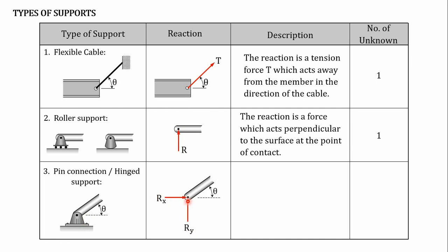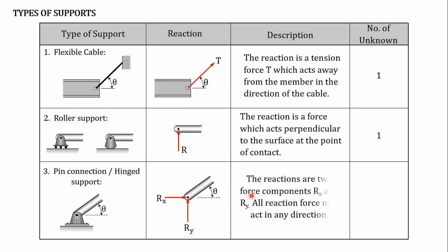But take note class, pin connection can rotate freely. When the bar rotates freely, there will be no resistance in moment. Therefore, walang resistance in moment dyan class. Only Rx and Ry. So, the reactions are two force components, Rx and Ry.